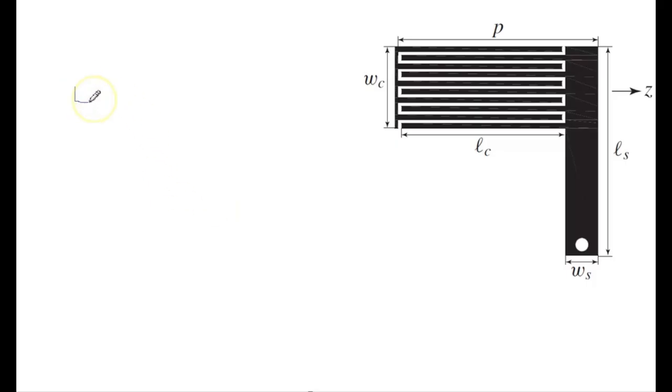Here, the left hand region supports the backward wave, and the right hand region supports the forward wave. These forward waves are the same as in a conventional transmission line, but backward waves are found in metamaterials, and the application of CRLH metamaterial is to design leaky wave antennas.